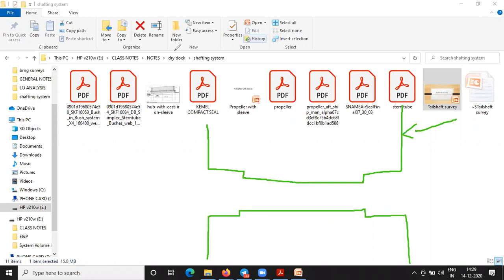Now you will have the bearings. The bearing is fitted like this. We can't insert the big bearing in one go. Why? Because there will be wear and tear. If you try to push the bearing completely through the tunnel, the bearings will have wear and tear, and stresses will be induced. When the stresses are there, what will happen? It will crack.